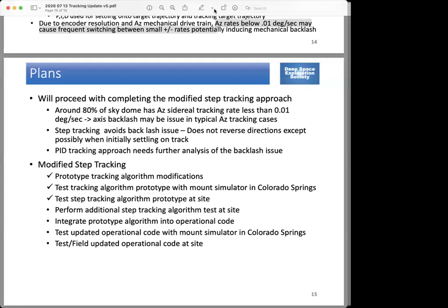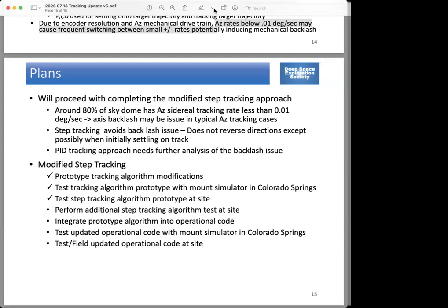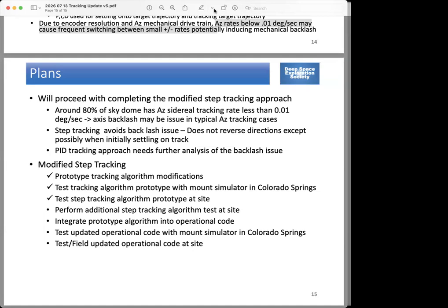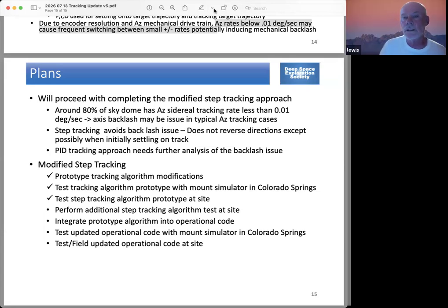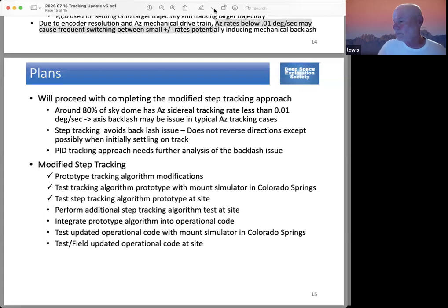And the sensor, it's a gray code encoder, absolute encoder, correct? Which are you talking about, the position sensor? Yes, position sensors. It's a resolver, and it's not an optical. It's a resolver type. Okay, what is the resolution there in degrees? 65,536, so it's about 16 bit. 0.005 degrees.